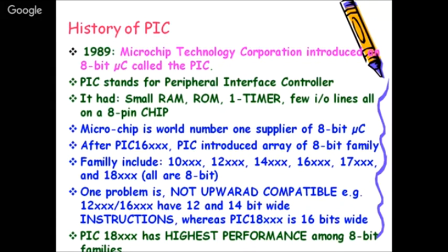There we'll understand this 14-bit wide, 12-bit wide. Because in case of Intel 8051, it is an 8-bit word that is used for data exchange or code exchange, instruction exchange or data exchange in RAM. Whereas you will see that in case of PIC, it is different. It uses a 16-bit wide or 14-bit wide word count.